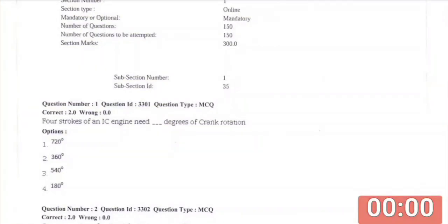In this stroke, the intake valve must be in the open position while the piston pulls an air-fuel mixture into the cylinder by producing a partial vacuum or negative pressure in the cylinder through its downward motion. Second stroke is compression stroke. This stroke begins at BDC or just at the end of the suction stroke and ends at TDC. In this stroke, the piston compresses the air-fuel mixture in preparation for ignition during the power stroke below. Both the intake and exhaust valves are closed during the compression stroke.